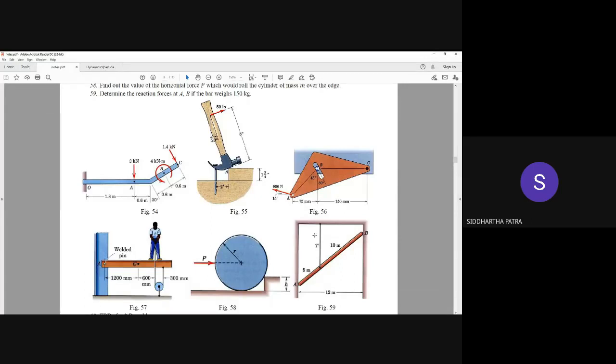Those who showed that circular peg right there, which is not part of the rigid body, that is an incorrect free body diagram, because that peg is a support itself. The support must be removed from the free body diagram.